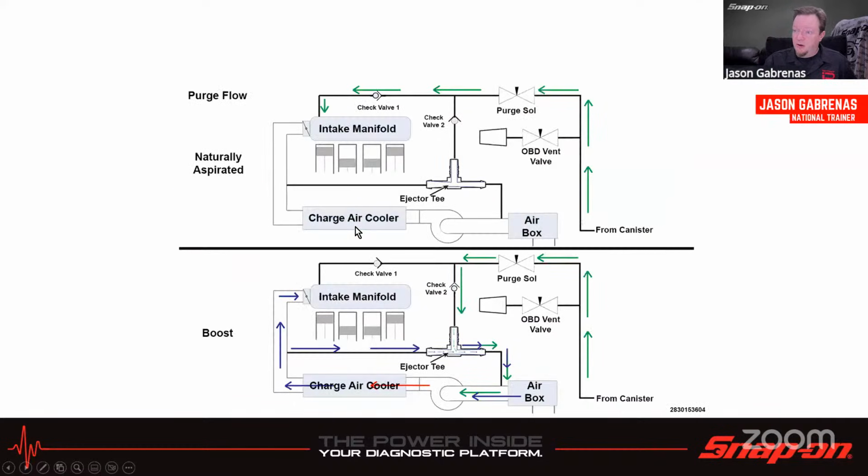To see that a little better, we have a little block diagram. It's going to come from the canister through the purge solenoid into the intake manifold, just like it normally would under naturally aspirated or non-boost conditions. Then under boost, instead of allowing it to go that way, we have a check valve here, which is going to close because it'll be under pressure, right?